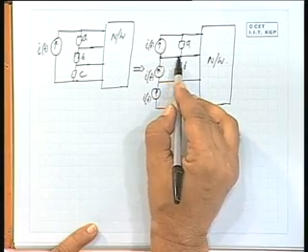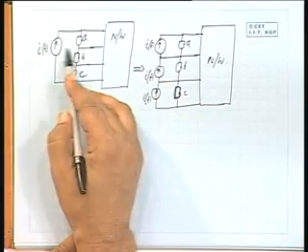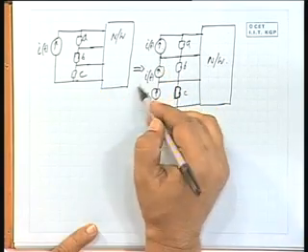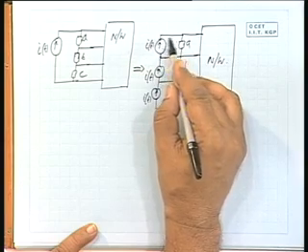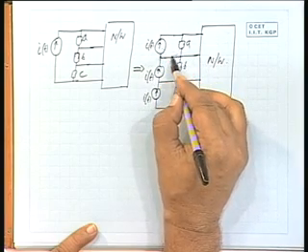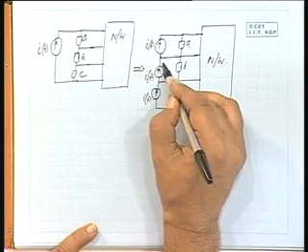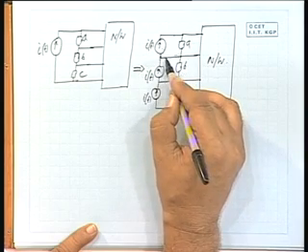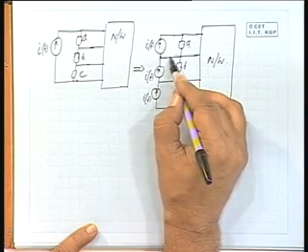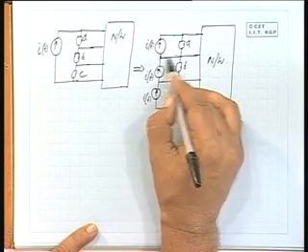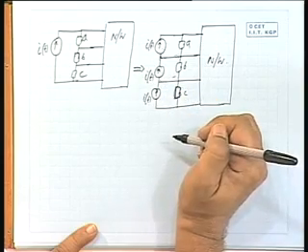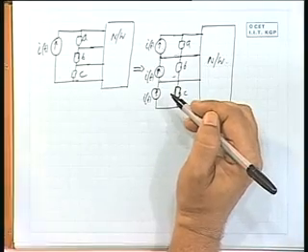This is an interconnection that I have put. It was not there earlier. How much is the current through this? I can assume a current IT coming this way and another current IT going this way, so they will cancel. So, there is no current. It is a virtual connection that I can make with 3 current sources.